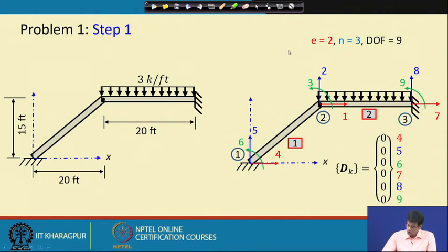So, if we choose this way, then my 1, 2, 3 is my unknown. You can see one thing here, that the first 3 degrees of freedom in the global stiffness matrix will be unknown. So, most likely we do not have to partition the matrix here, or we have to partition it, but the row and column operations we probably need not do.